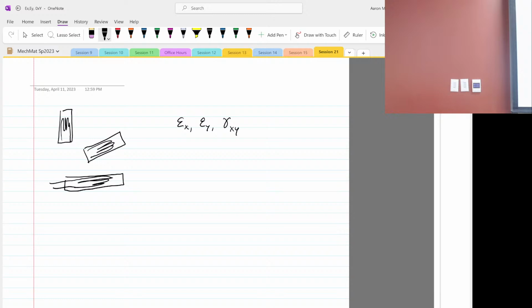We are looking at a shear stress that balances against these bending stresses. And so if you're at the neutral axis, you have all these bending stresses that you're fighting against, or balancing against. But if you're at the top edge or the bottom edge, there's nothing there to balance, because it's just air there. So the transverse shear stress ends up being 0 at the top and the bottom, and it's max at the neutral axis.